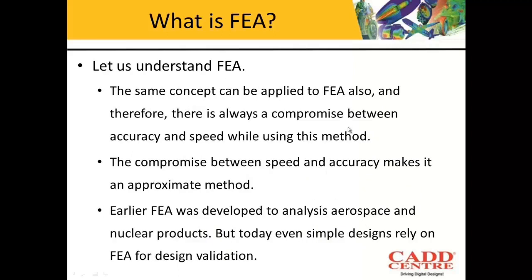So the same concept we can apply in FEA. If we want to have a better solution in FEA, we need to have more number of elements or more number of divisions. But if we divide the object into more number of elements, we will also have to spend more time in calculating the answer. So FEA is a compromise between accuracy and speed,